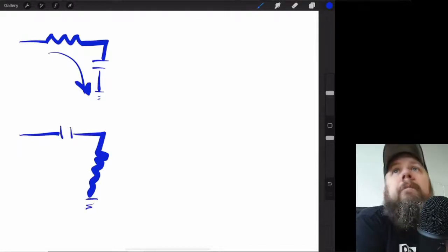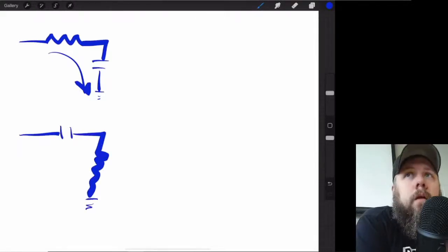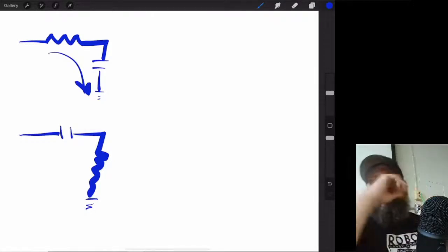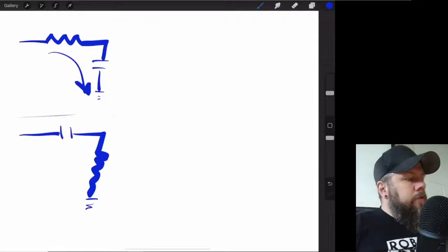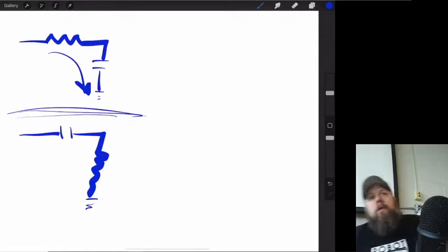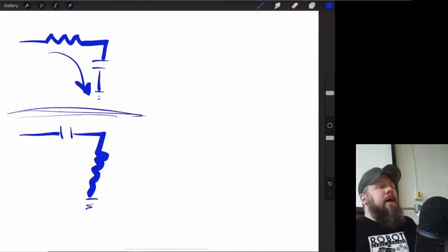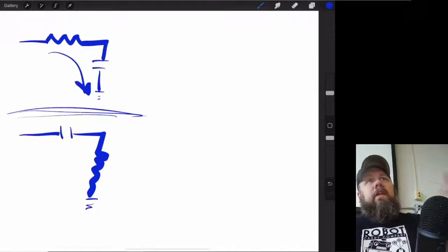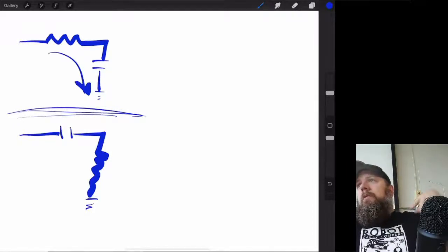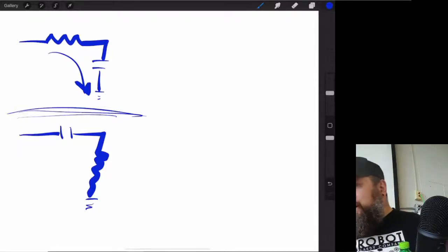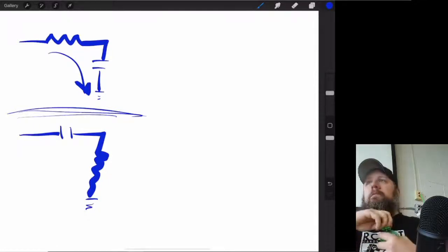What is that? It's a high pass, right? All the high frequencies are getting through there pretty easy. So just think about your resistor networks, and that capacitor makes a capacitive reactance that is inversely related to your frequency. As frequency goes up, it goes down.